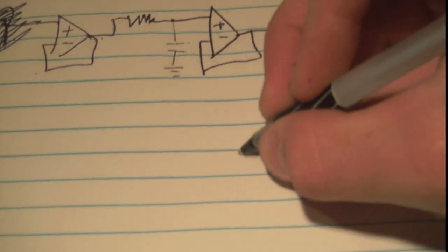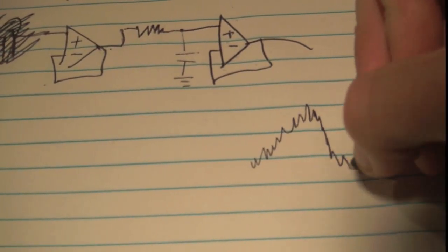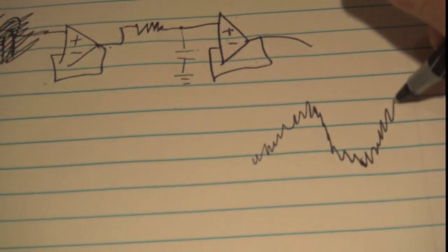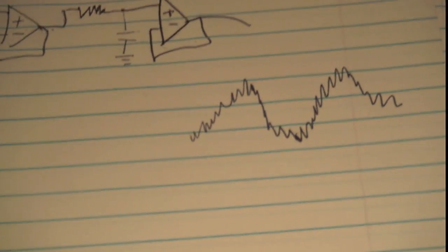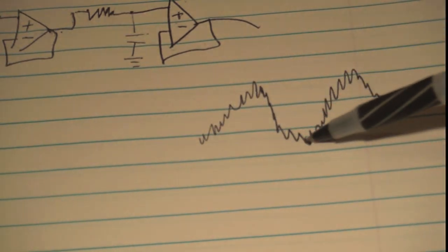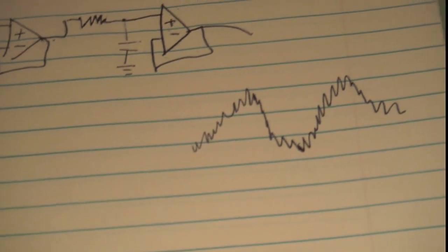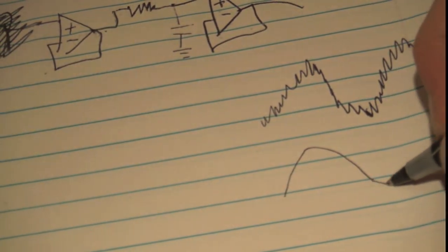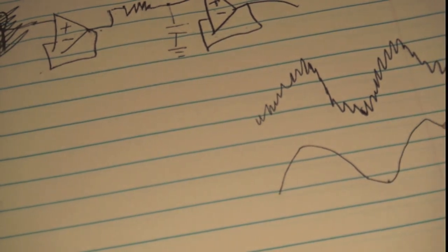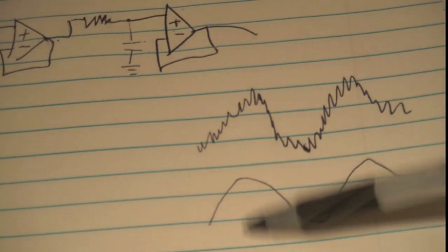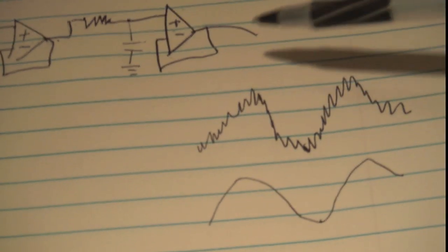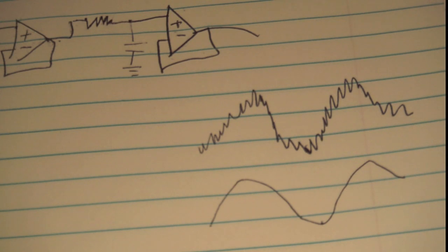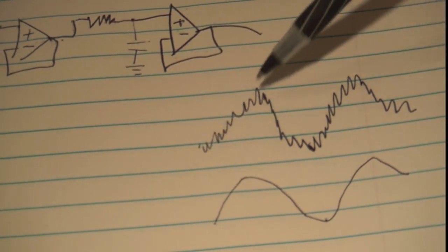say we have something like an AM modulation, okay? So we have a high frequency making a low frequency waveform, okay? What the low-pass filter is going to do is it's going to attenuate this high-frequency signal, pardon the bad drawing, and it's going to let the low frequency pass. Okay, so you're going to get something like that on the output. So what effectively this is, we're taking the average, okay, because think of the average of this signal without the high-frequency overlay. So same thing with PWM.